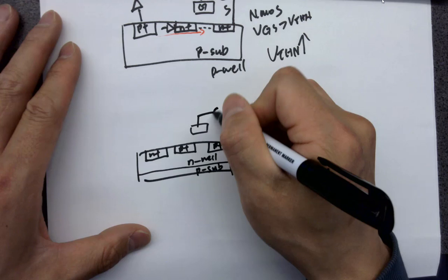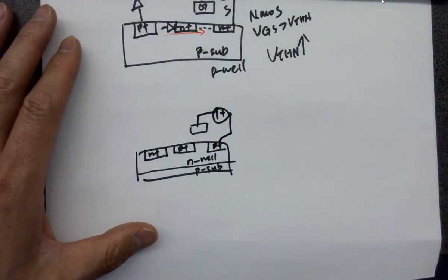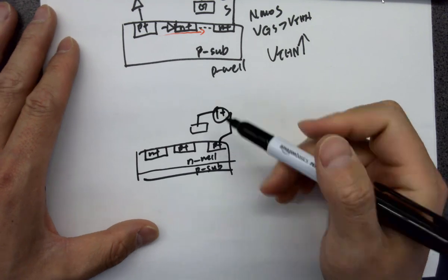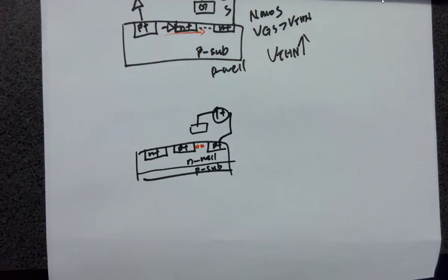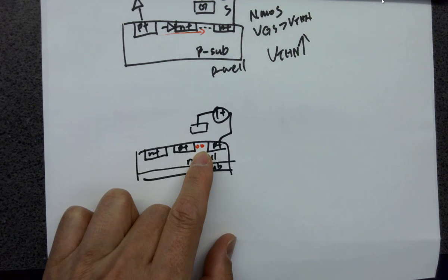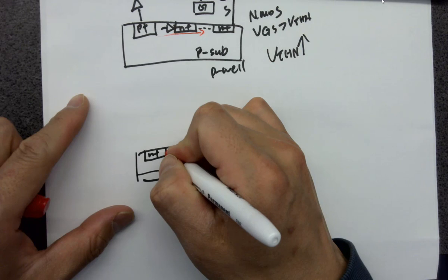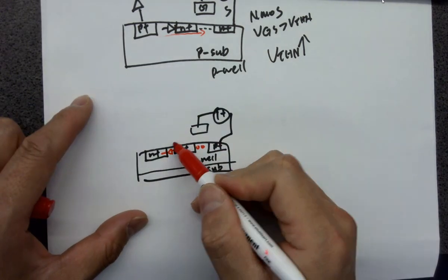it's a very similar concept. Okay, you need a negative voltage from gate to source in the PMOS in order to attract holes. So the PMOS channel has holes in it, okay? And because of the little p-n junction here, the parasitic diode, it's a p and n, right? It's a p and n.